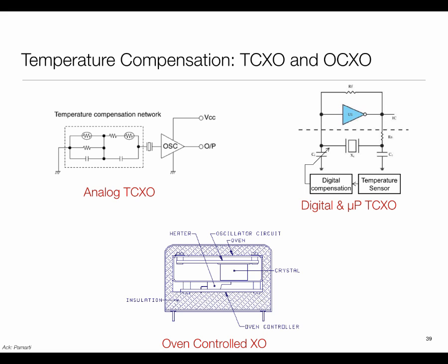In particular, certain resistance values, literally potentiometers, are calibrated in the factory. They take the part, subject it to a number of temperature settings, see what the drift was, come up with what the compensation setting should be, tweak this analog circuitry, and then ship the product. And that suddenly raises the cost from literally a few cents to a few dollars, because you're putting effort into it.